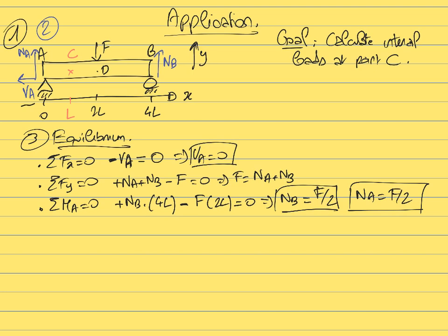We can always find it usually by writing that the sum of the moments is equal to 0. So if you're not sure, I would recommend you just avoid saying that those frames are symmetric. You never need to assume that. You can achieve the result simply by writing the three conditions of equilibrium that you have for the system that you're isolating.